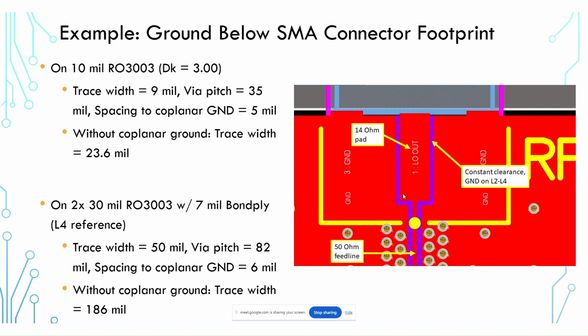Okay. Now, one thing that we're doing along this RF line is basically what was done in the other mixed signal board that I showed earlier with the impedance matching network, which is basically just placing some vias along this line in order to confine the field around this trace and help prevent any sort of potential crosstalk from anything else that's nearby, and then prevent strong radiation from this trace. Now, that sets the impedance of this line to 50 ohms, but then when we get that 50 ohm line over here to our connector, we then have this interface here where we then have the potential for some reflection. And so we want to overcome that.